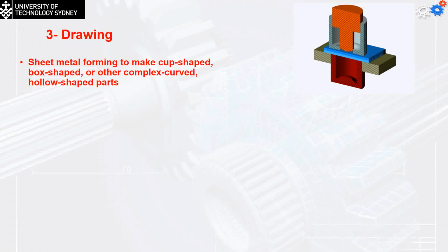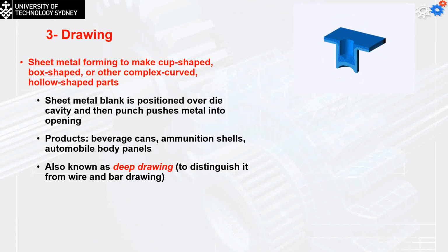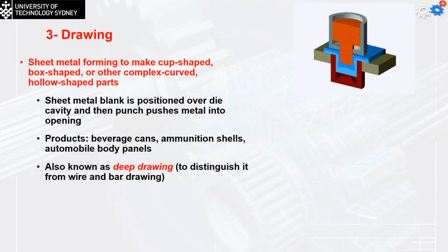And that's actually what we saw last time with the making of the cylinder for the gas bottle. So we hold the part, we send in the punch, and this will cause the part to take the cylindrical shape. The clearance in the drawing usually is going to be equal to 1.1 multiplied by the thickness of the stock we are using.